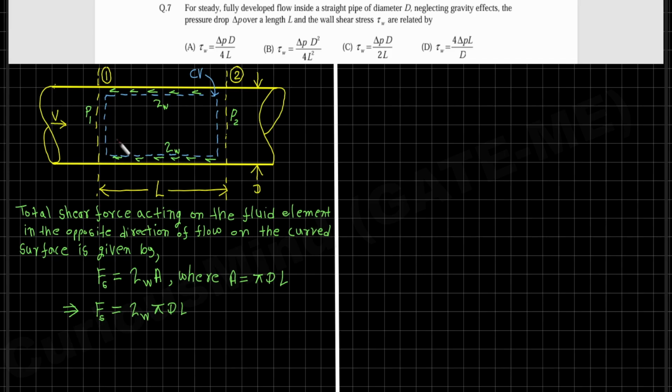Now we would write the expressions of the forces that would act on these surfaces of the fluid element. And these surfaces are actually circular surfaces of diameter d, because when we look from here, we would see a disk of fluid element of diameter d. And similarly here, when we look from here, we would see a disk of fluid of diameter d. And just in the immediate vicinity of these circular surfaces of diameter d are the pressures of the fluid outside of this fluid element, P1 and P2.